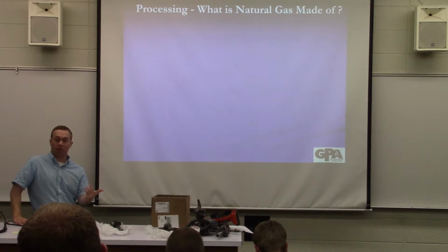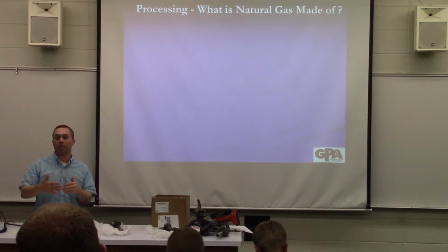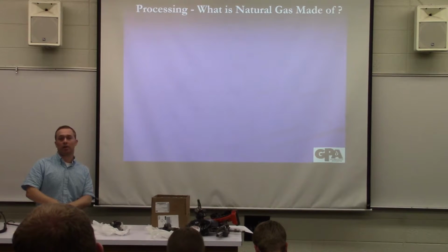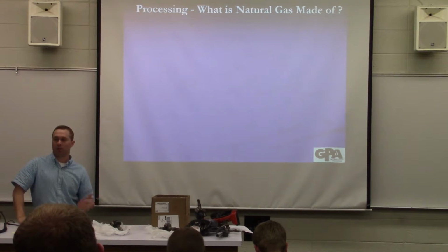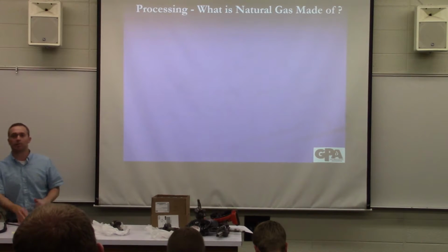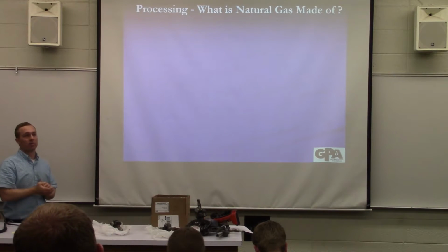It's something Dr. Baxter and I were just talking about the other day, though, is sometimes carbon dioxide, even if you meet the pipeline specs, say you're at 1.5% carbon dioxide, it prevents you from recovering as much of the other natural gas liquid components. And so sometimes you'll want to remove some carbon dioxide anyway, even if you meet the pipeline spec. What other components might be in it that you wouldn't want in there? Would there be hydrogen sulfide in there? Yeah, so sometimes there's hydrogen sulfide.